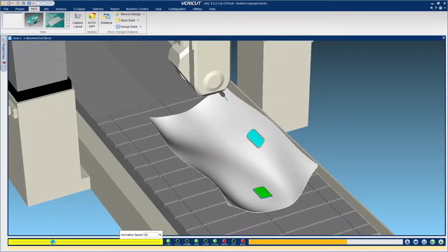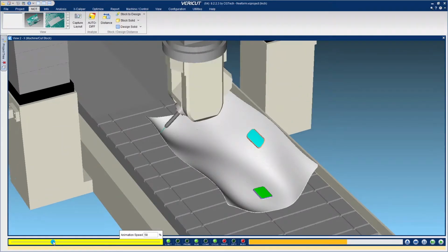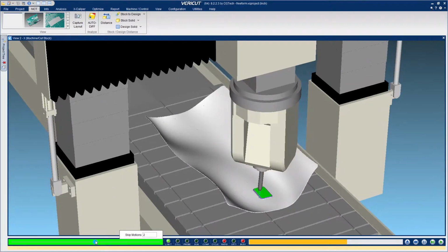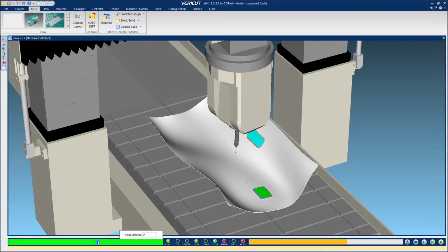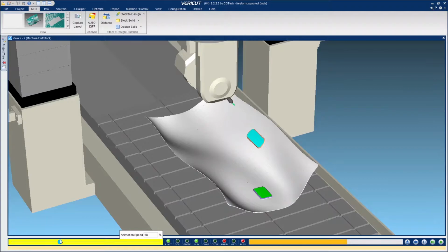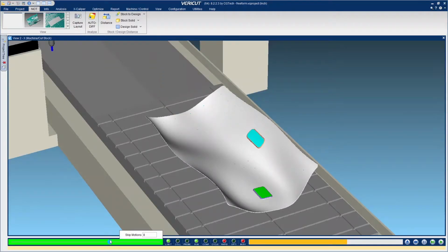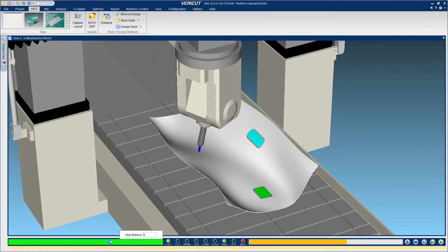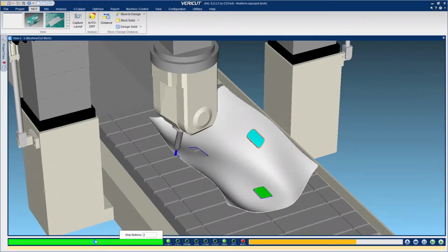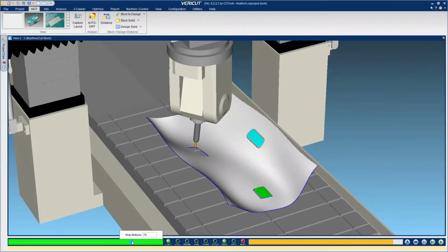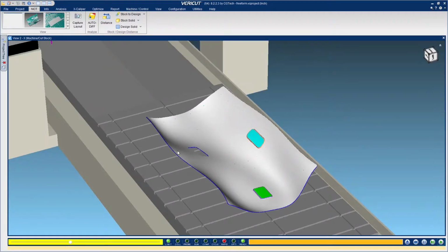Next, we're going to drill the holes using that 1/4" drill. This is a 5-axis drilling operation, which NCT handles just fine. And when that's done, it's going to grab the 100-degree countersink and countersink all of those holes. And using a 1" end mill, we'll hog out that pocket. Then we'll finish the same pocket and then finish the periphery of the part as well. Again, a full 5-axis operation. NCT handles it just fine. And then that went really quick, it came in here and machined the chamfer on the cutout.